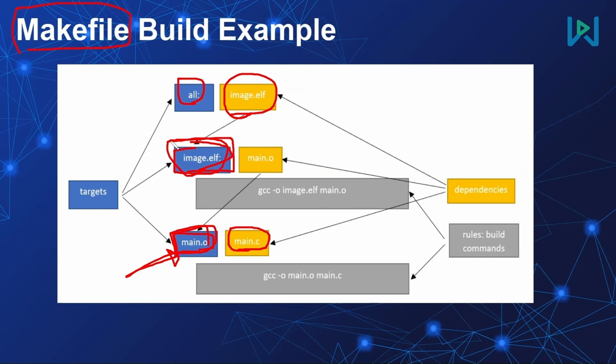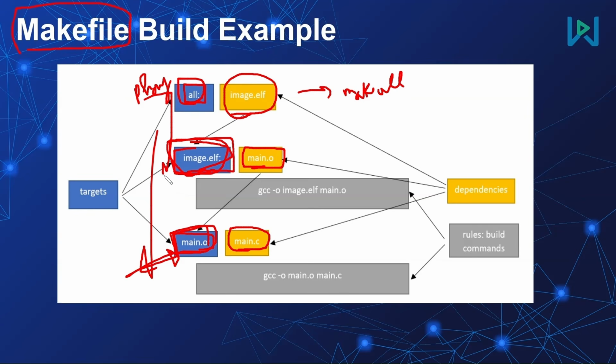This one will represent the final ELF image coming out of the linking stage of the different objects of our embedded system project. And finally, this .PHONY target, this one, will be our entry point to trigger the execution of our Makefile rules. So we can invoke make all like this, and then the Makefile will start parsing, evaluating, and running the different rules.